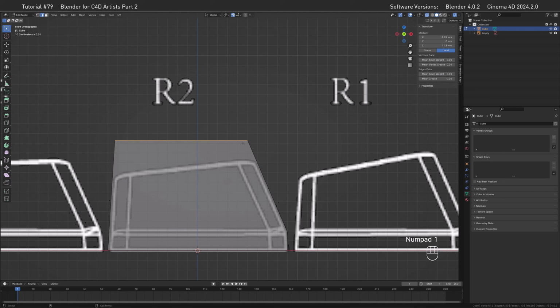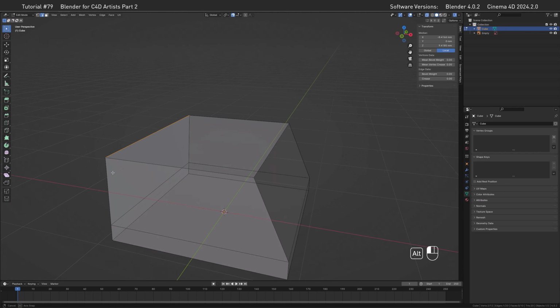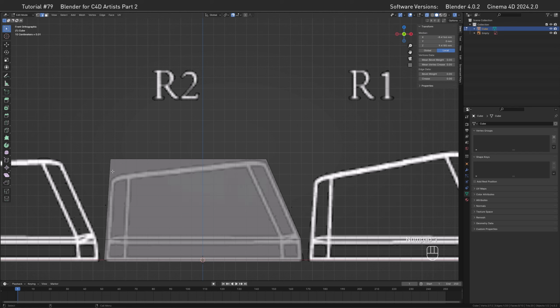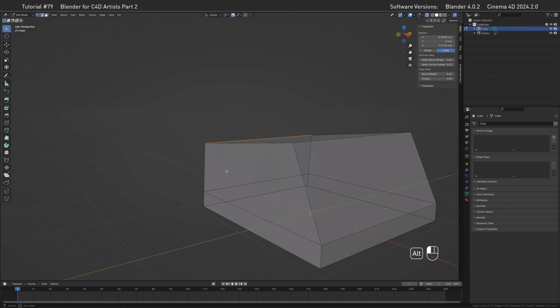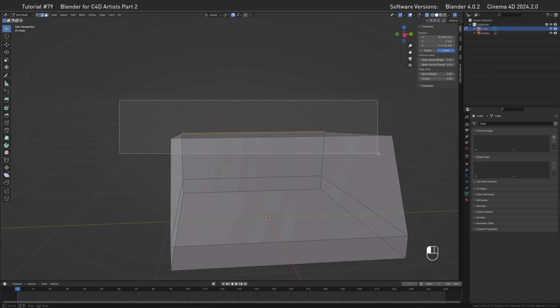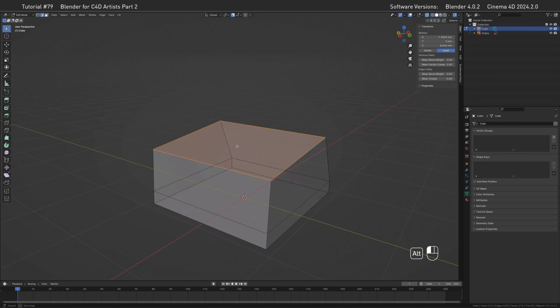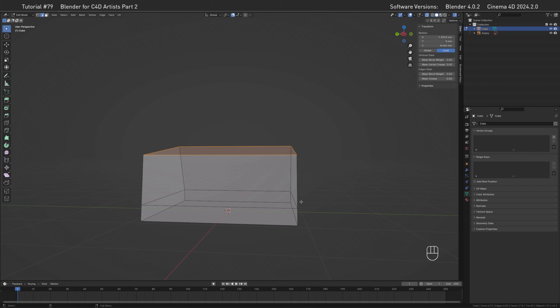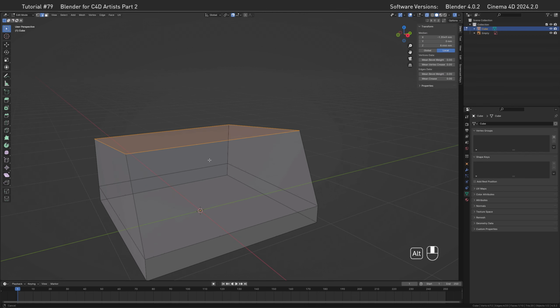So let's actually do that by hitting G G in the side view so we can see where we are moving to roughly about here. Then select the back edge here and then G G move it down to about here. And this gives us a very nice key shape. What we want to do next is get the top part of our keycap sort of squared. So we get a flanked side of both sides of the keycap as well.